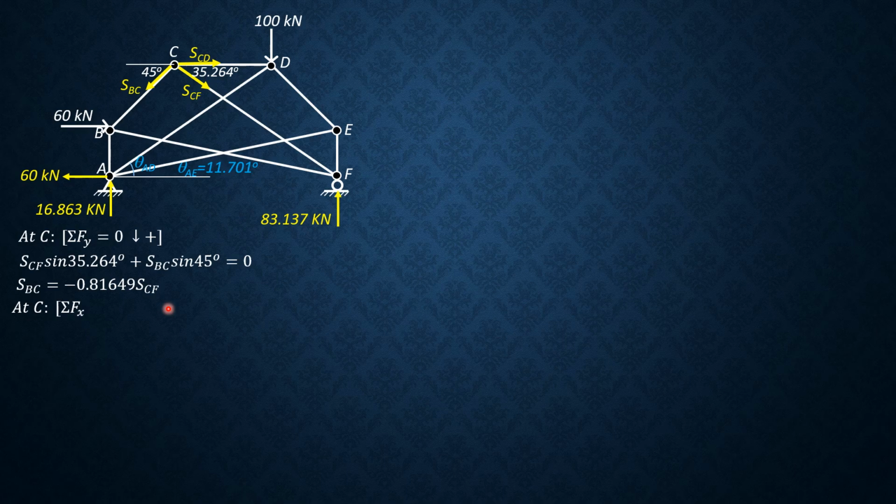Then at C, summation forces X equals 0. SCD plus SCF cosine of 35.264 equals SBC, which is negative 0.81649 of SCF cosine of 45 degrees.